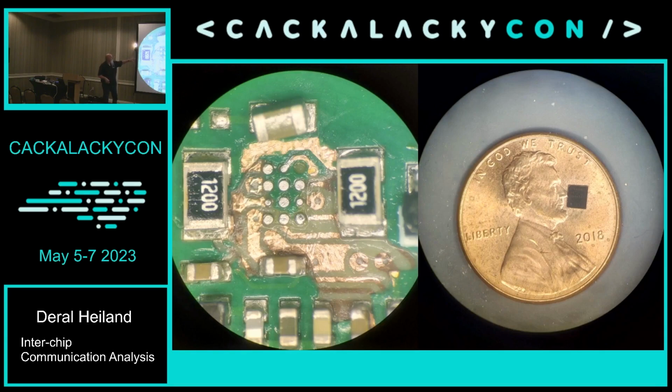And that's what we're seeing through 3 layers. And I just did this with a scribe, actually scraping the circuit board as I went down. Just to give you an idea, that whole footprint there is that chip. So you can see it's a pretty small area. But I've done this a number of times, even in this particular project where I had runs running through lower multi-layers. And I didn't have an X-ray machine or anything like that, so it was literally picking spots on the board where I thought the runs would go and start delayering the board until I found the tap points on the circuit board.